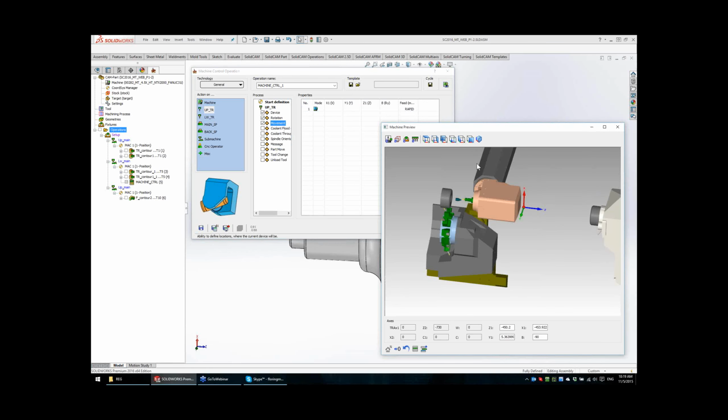Again, I will use the machine preview. So B-axis is already in a good position, minus 90 degrees. I'm just sending the X using control with steps of 100. I'm sending it to 0.